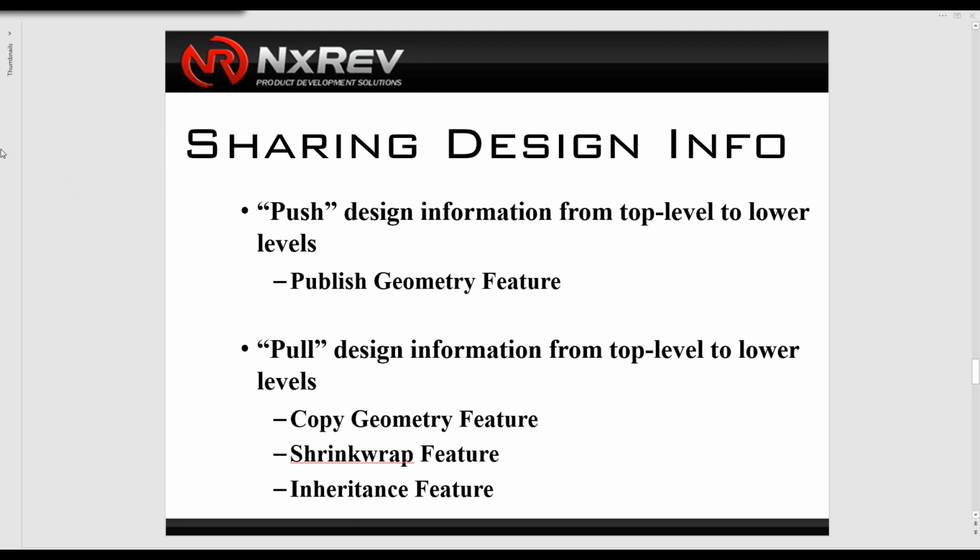Pulling design information can include copy geometry itself, so you can copy references that are stored in the published geometry features onto your components. It's useful in a concurrent design environment. And it's used to communicate all those geometric references, information, and user-defined parameters to and from parts, skeleton models, and assemblies. This also enables you to reduce the amount of data in session, so you don't have to open up the entire reference source model. Right.